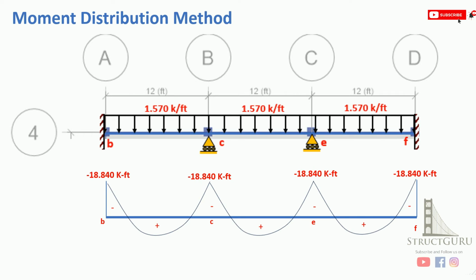So in order to give a realistic meaning to this bending moment diagram, let's inverse this bending moment. So in this case, the positive moments are represented below the XY line and the negative moments are represented above the XY line. So this actually gives you the clear picture when the load is applied in this manner, it will try to deflect downwards. So positive moments are associated with downward deflections, and the negative moments are associated with upward deflection.